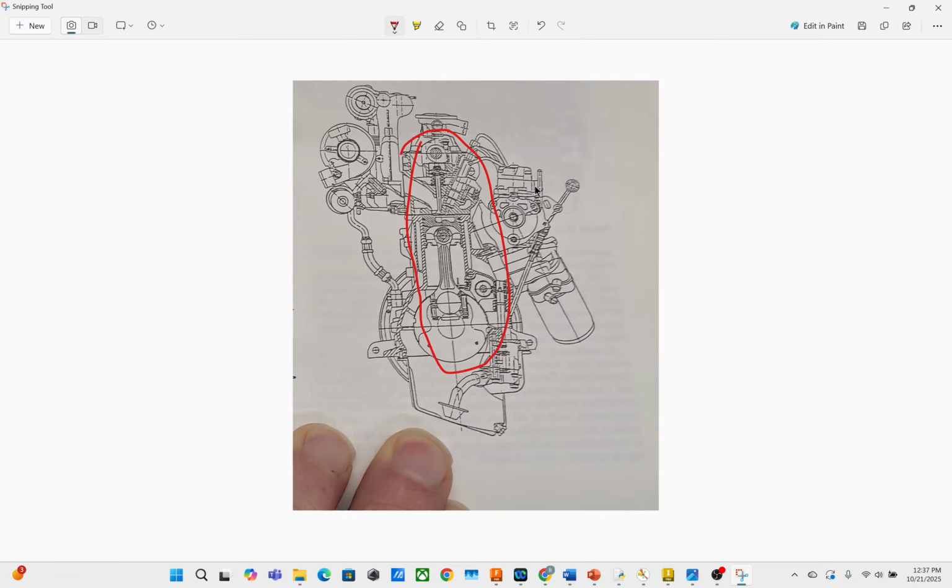But I also don't want a timing belt to cause the end of the engine, which brings me to getting rid of the overhead cam, which is a very simple, very cost-effective way to do everything because there's very few moving parts. It's just a cam pushing directly on valves. So how does that look?